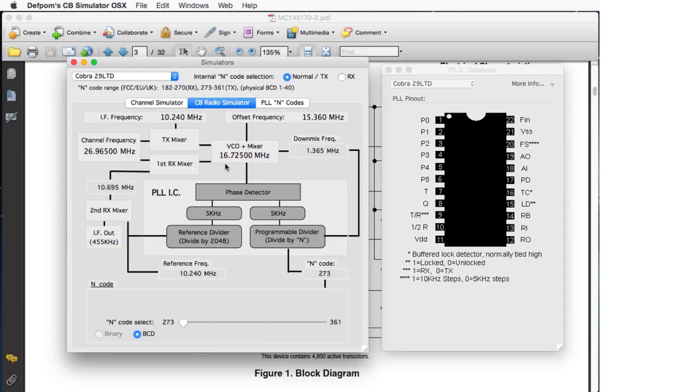Okay. All that does is it proves whether the VCO itself works correctly, and it also means you can check this frequency here to make sure that it's being downmixed correctly back to the PLL, that FN frequency. You can verify that makes sense.